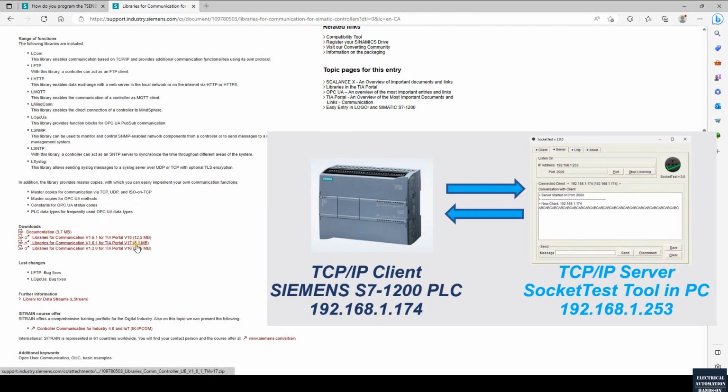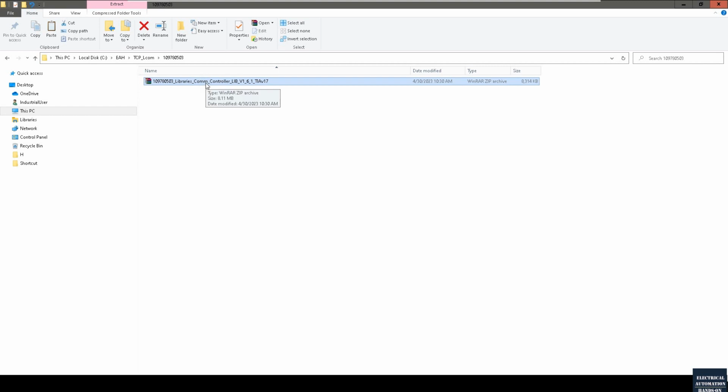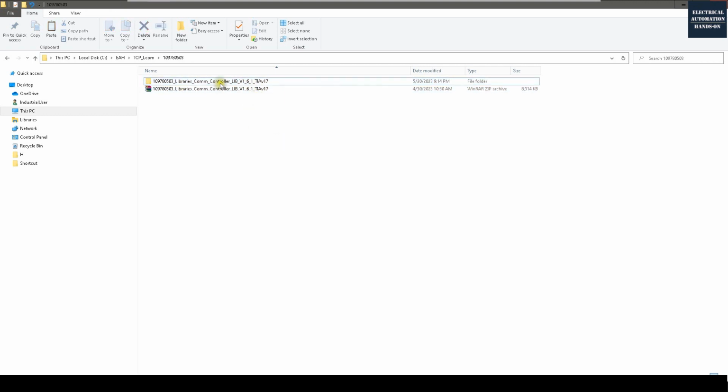In this video, I will use version 17 and a 1200 PLC, and use my laptop running as the TCP/IP server and the 1200 PLC running as the TCP/IP client. Okay, let's download and let's go to the TIA Portal. After we download this file and unzip it, we will see this file is not a project, it's a library. So it's a good time to show how we can import this library and set up a project.